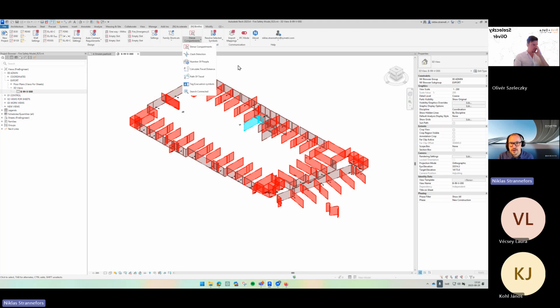So for instance, dense compartment does not work with IFCs, because when we do Revit oversimplified, we check the wall, if the wall has things hosted to it, what objects are hosted to it, et cetera. With IFC, there are not those connections, so we don't really have that one. But you can turn IFC mode on and off, and everything with a red marker works with ArchiCAD, like an IFC for ArchiCAD, if you turn this on.